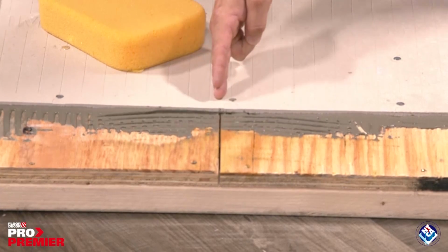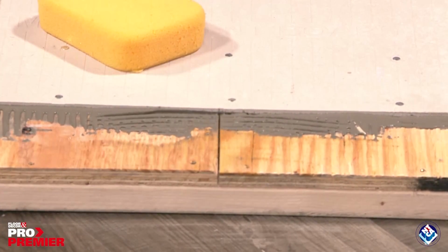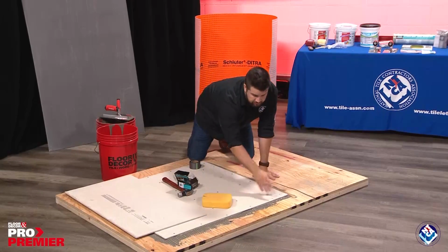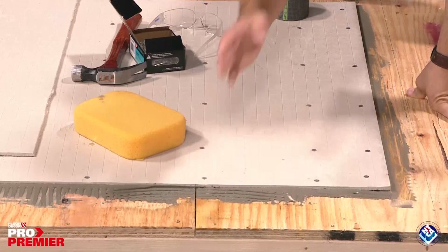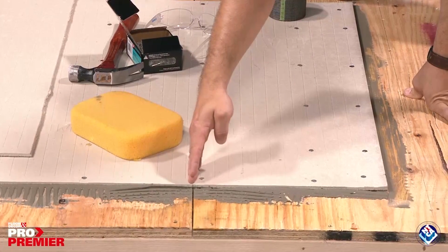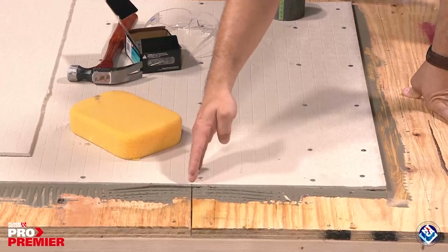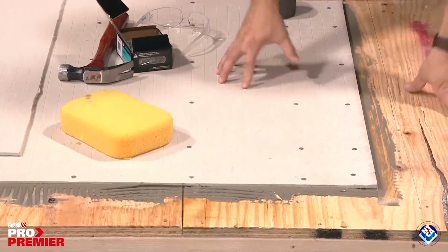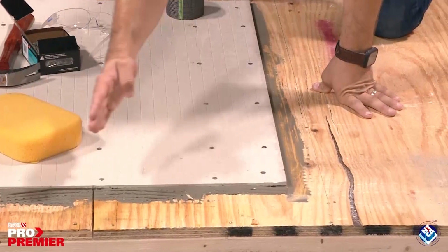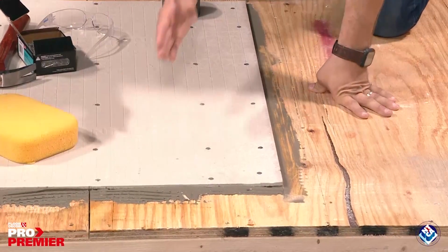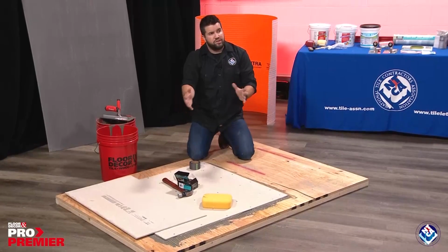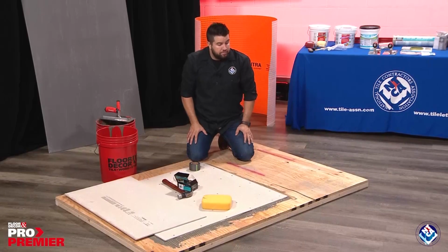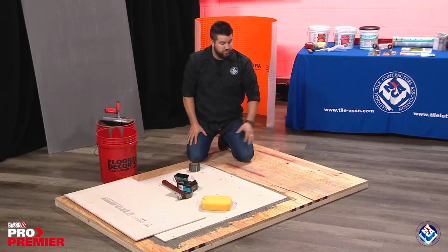They've got about 1/8 of an inch, and that's going to allow that proper movement of the subfloor, the expansion and contraction that's required in the subfloor. So we've honored that, and we've also taken this joint in the plywood panels into consideration when we started laying out our backer board. I did not start a sheet of backer board in line with the joint on the subfloor. You always want to stagger your joints when installing backer board over top of plywood or any kind of subfloor like this.